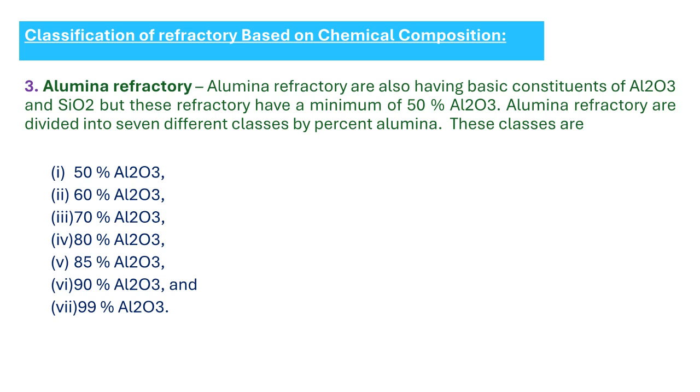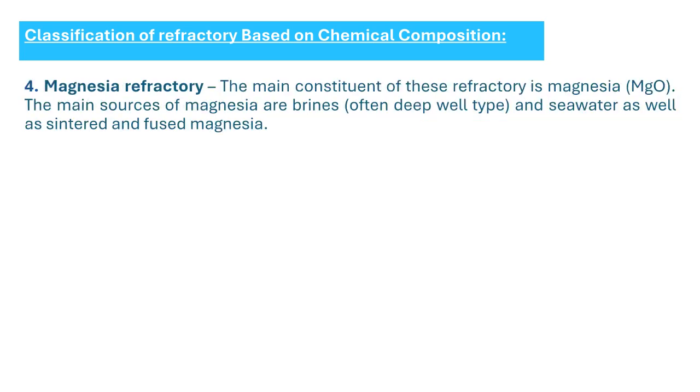As the alumina content increases, so do the temperature capability, strength, and cost. So, the choice depends on balancing performance requirements with budget constraints. Because of their high strength and heat resistance, alumina refractories are essential for demanding applications like steel furnaces, electric furnaces, and high-temperature industrial kilns.